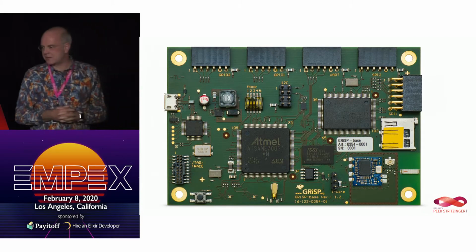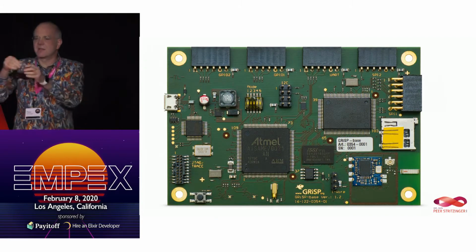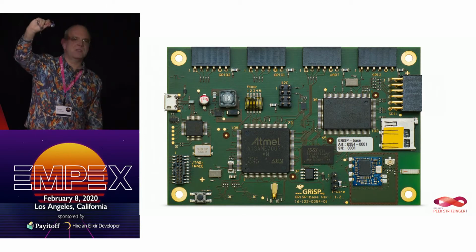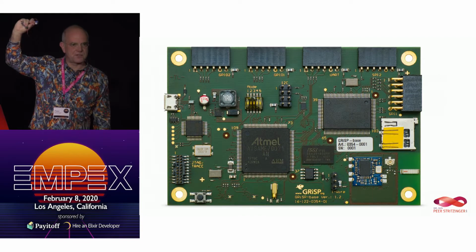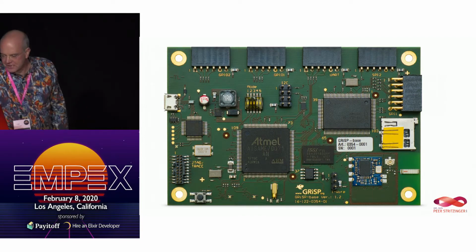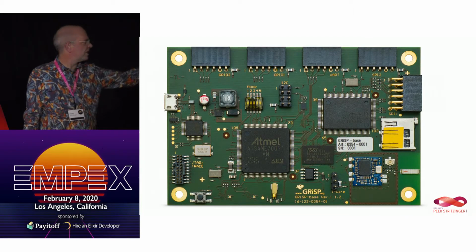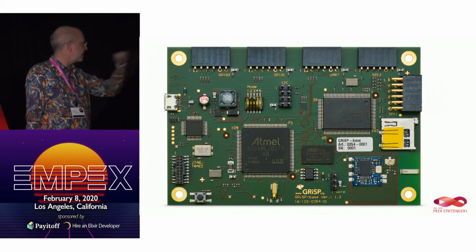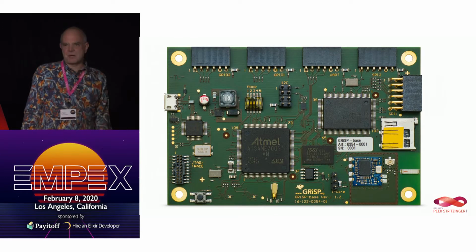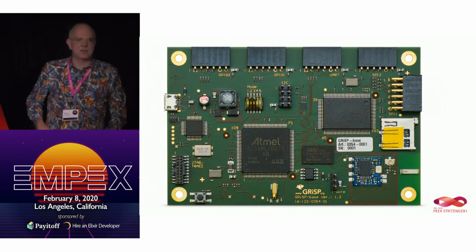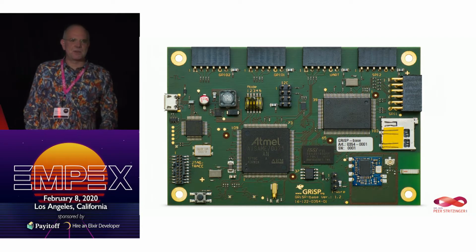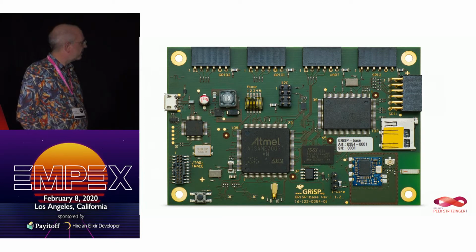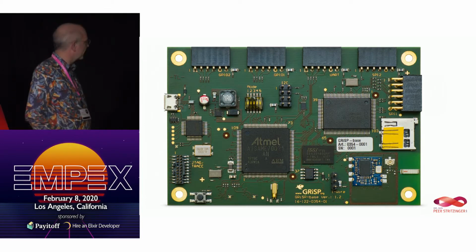Those are so-called Pmod connectors, which are these little boards, about this size. And you get hundreds of sensors and actuators for those. And they have different kinds. There's GPIO, there's UART, there's SPI, there's I2C, there's Wi-Fi on the board. We have an SD card to boot from. CPU about 200 megahertz, or 300 megahertz actually. Effectively, it's running at 100 megahertz because we needed to work around a bug in the USB chip, which was kind of annoying. That's why we don't use that CPU anymore in GRiSP 2.